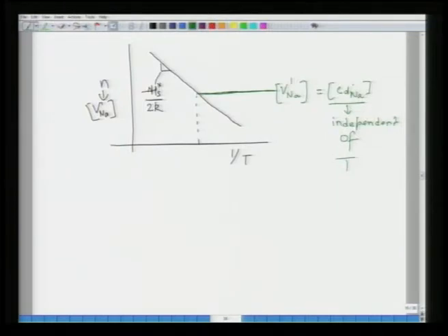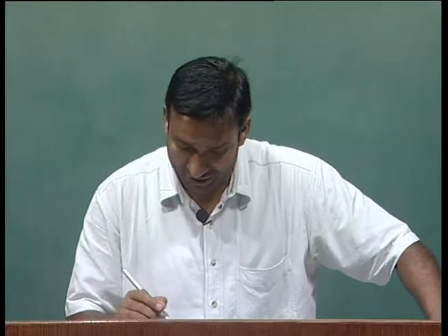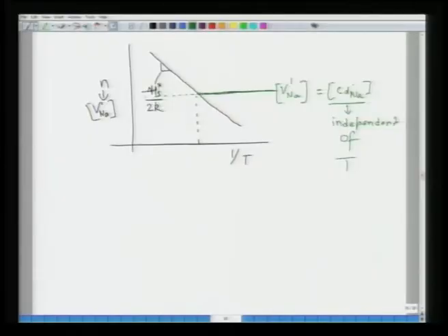Now, however, there is going to be a point when thermally created vacancies due to the Schottky effect take over. After a certain temperature, the thermally created vacancies start creeping in and start dominating, so the curve will follow like this. After this point, V_Na is governed by temperature.